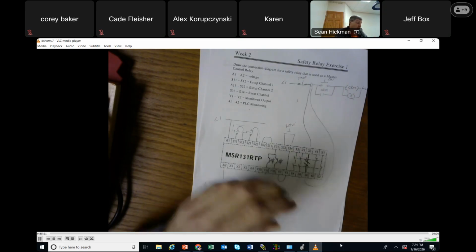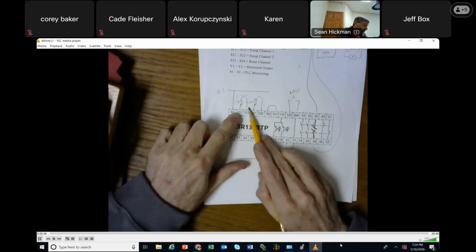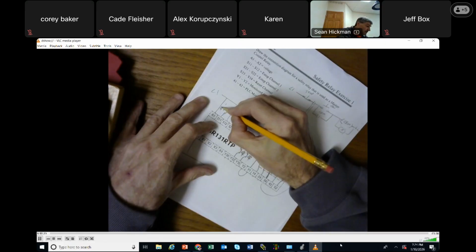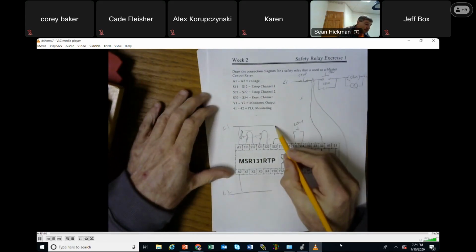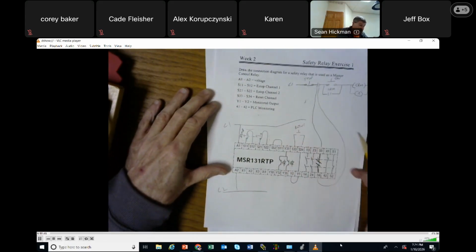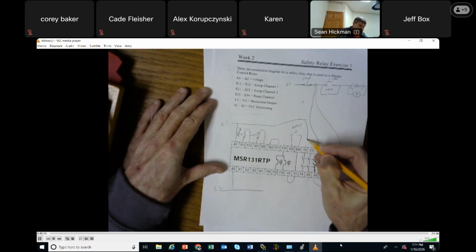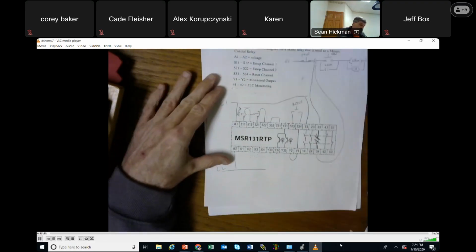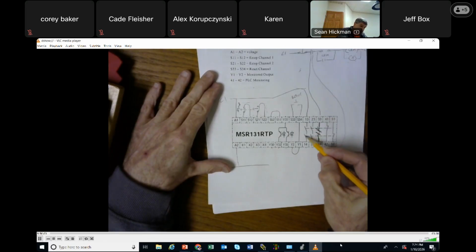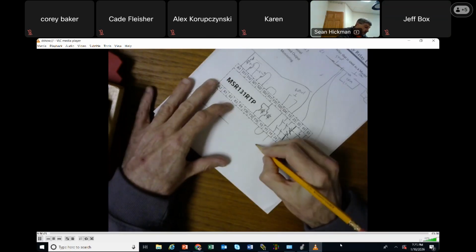Okay. Well, the reset turns it on, and the e-stop turns it off. That's it. The reset turns it on, the e-stop turns it off. Well, what you could do, here's my line 1, kind of running around there. You could just take this line 1 and run it into, let's say, this contact. This is a completely separate way. We got 3 sets of contacts. You could just run this through here and run this into your CRM.